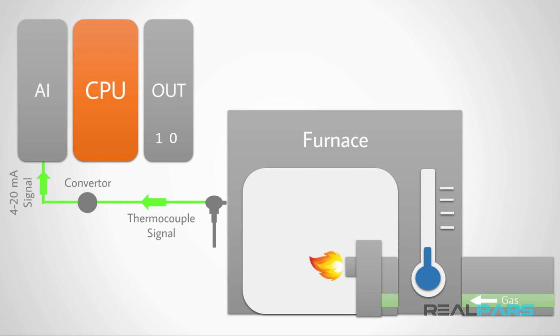So, in order to control the heat generated by the burner, and therefore the amount of heat of the furnace, we need to somehow control the amount of the incoming gas to the burner. In order to do so, we can use a special valve called a proportional valve. The way this valve works is it gets in the way of the incoming gas to the burner, and in this case, the amount the valve opens up will control the amount of the incoming gas to the burner.